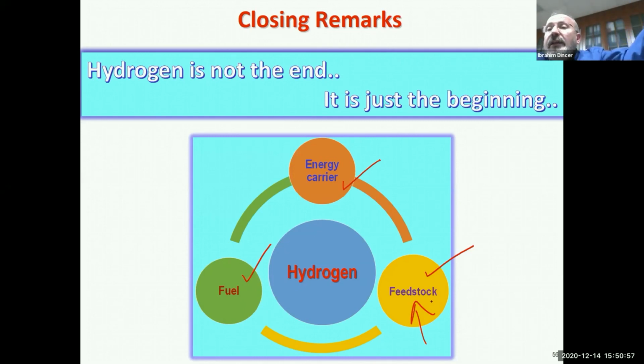And ammonia is not new in the refrigeration sector. It has been used for so many years, even before CFCs actually came in. We had ammonia being used in household fridges. There is not any single fatal event reported. So when you look at it, every chemical has some safety concerns, and ammonia has, yes, I accept. So just like other chemicals.